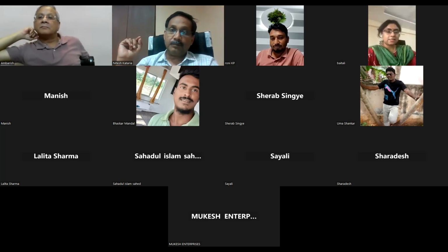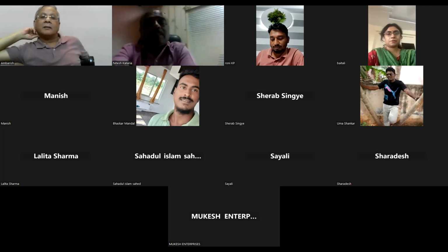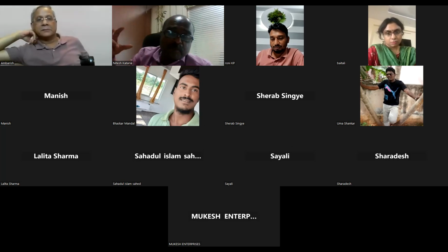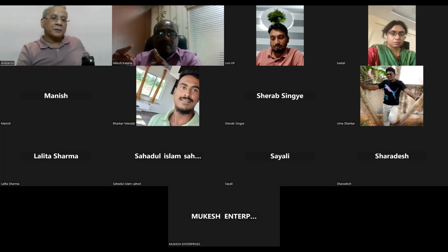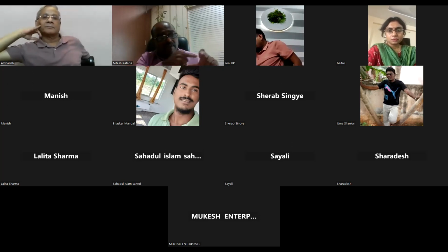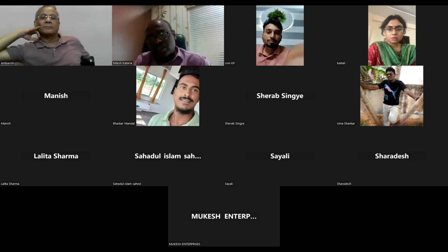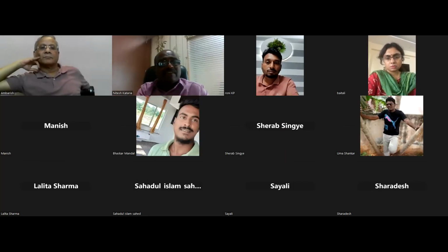And in one of the slides, I was explaining something about the backup hex. Can you please elucidate on that point? Backup hex is always referred to. See, there are two kinds of connections. One is a progressive connection, where the nut will have a male nipple and the adapter will have an internal thread. So that is called a progressive connection. Whereas on the reverse, like UNF threads, the adapter will have a male thread and the nipple will have an internal thread. So that is a regressive connection.